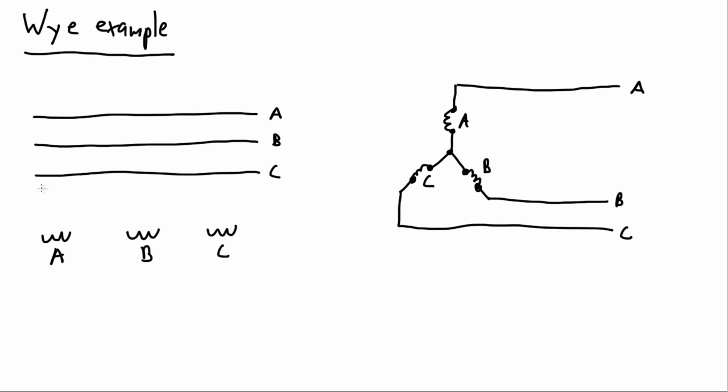So this now visually, after we worked with the delta, should seem actually really kind of painfully obvious. The A incoming power line has a single connection to our A inductor. So A gets connected to A. Very simple, single connection right there. B incoming power line connected, single connection straight to the B inductor. And likewise for C. C connects straight to C. And we can see that visually with our Y really, really simply. So we've managed those connections here that we're Xing off. Now, our only other point of connection is this middle point right here. What exactly are we going to do here?